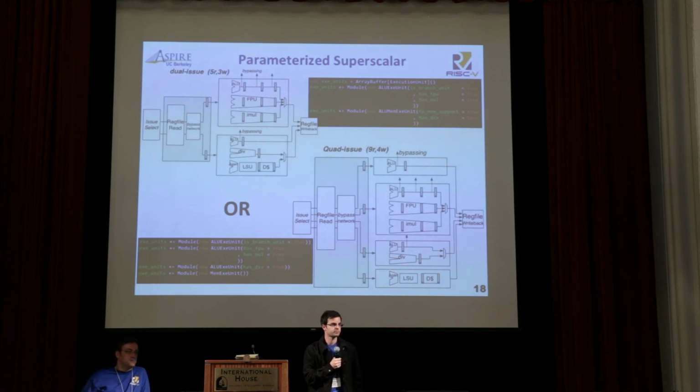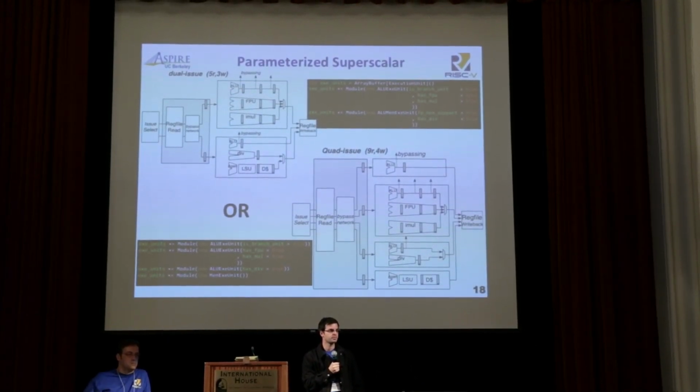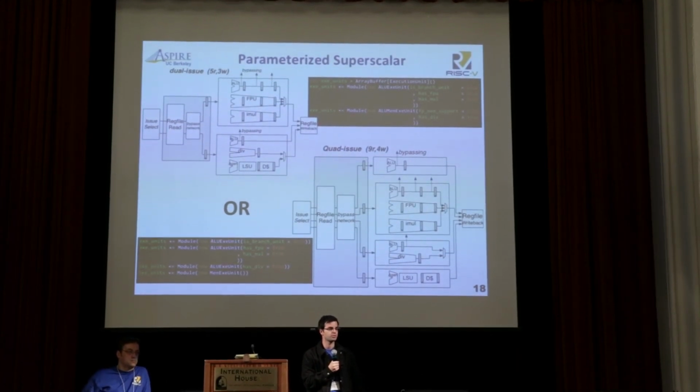Then what about the performance compared to other tools such as Verilator or some DPI functions? Right, so when we started Chisel, I think Verilator was not in a good place. The C++ that Chisel generates is really fast, in part because it's two-state and in part because it's not an event queue, it's a straight flow through the diagram. We are interested in reevaluating that decision now that Verilator is a much more serious contender, but I don't have a comparison of Verilator versus Chisel C++. Okay.